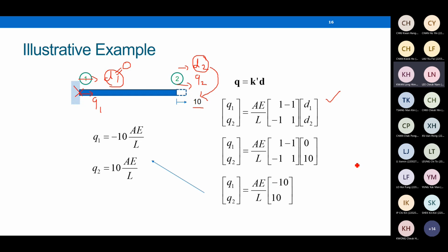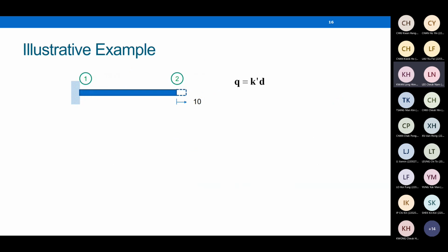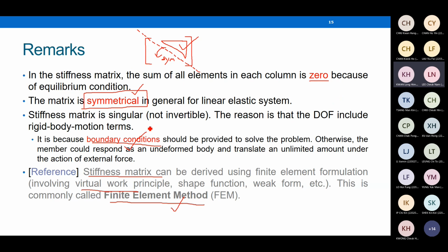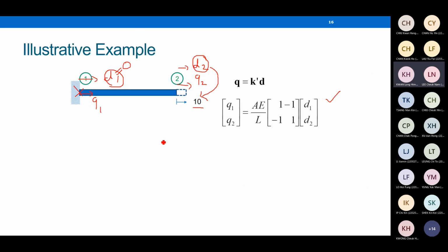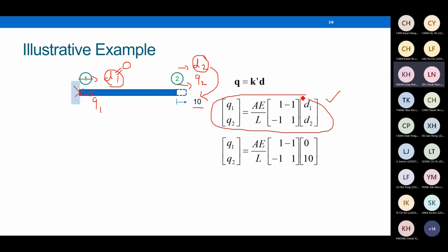It depends on what information you have. If you know the force, then you can use it to find the displacement. If you know the displacement, then you can use it to find the forces. Okay, this is just an illustration to show you how to use the equation. As said before, you can't use the equation directly. You need to provide some conditions, boundary conditions. Otherwise, you can't solve the problems. When you just take a look at this problem, you cannot get anything. You have to input some support conditions or the loading. Otherwise, you can't solve it.